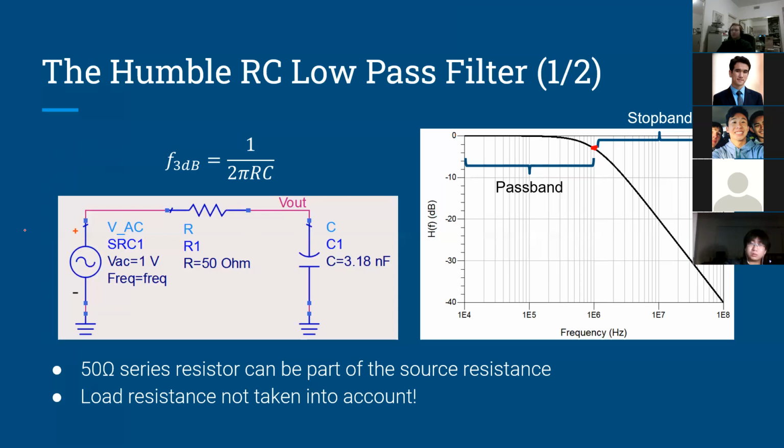All right, so remember what we've been doing is we've always had a source resistance in series with our voltage source. Because at RF frequencies, it's very difficult to get our source resistance close to 0. That might be easy at like DC or low frequencies, but at RF frequencies, you're not going to do it.